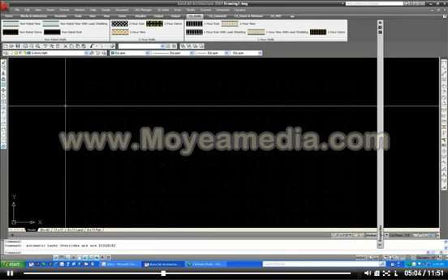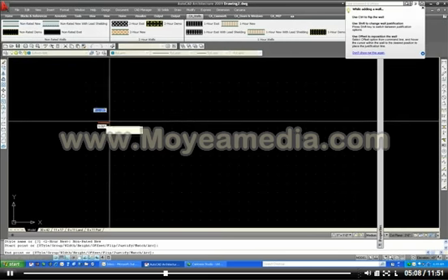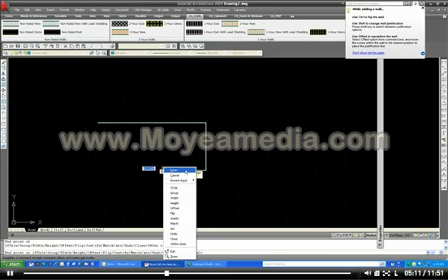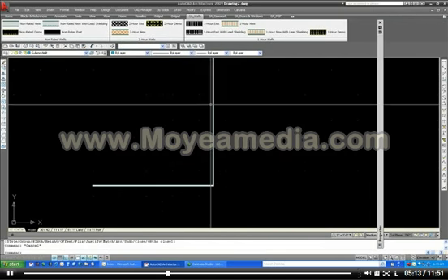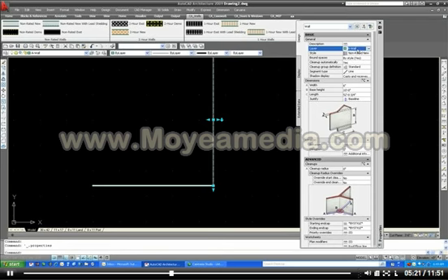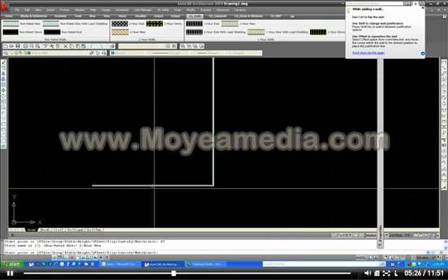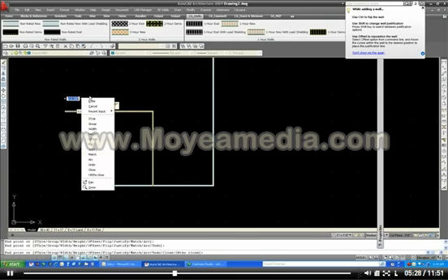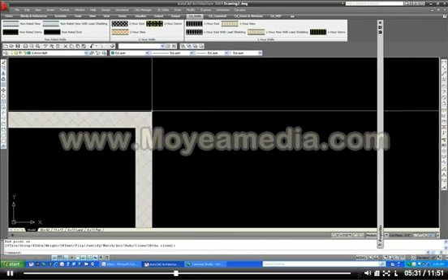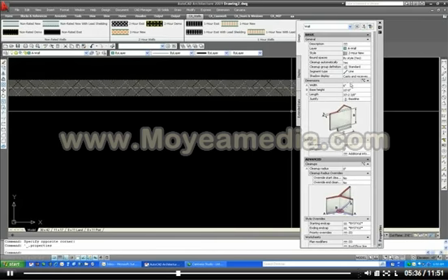So now if I select a new wall, I'll select this non-rated new wall over here, and I just begin to draw my walls. You can see here that this is an actual non-rated new wall, and it comes in on the correct layer, A-wall. Same thing over here with the 2-hour rated wall. Say I want to draw a 2-hour rated wall coming across here. As you can see, this wall is now a 2-hour rated wall. It comes in with the correct style and the correct layer.